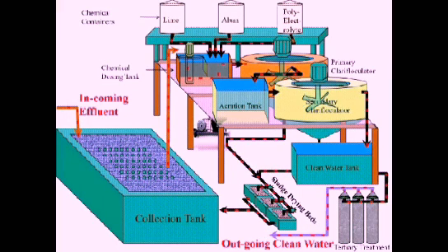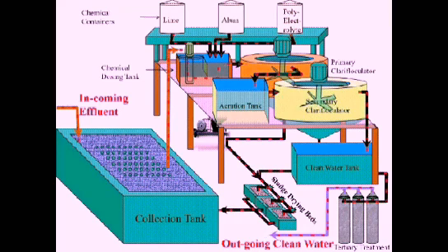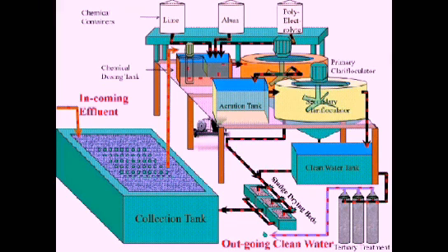For pH and TDS, we can test the water sample daily. It will help us regulate the dosing of the chemicals at various stages of treatment. However, for the other vital parameters, we need to send the water sample to certified labs at least once in a month, as is also defined in India in the water and air consents which we get from the Pollution Control Department.